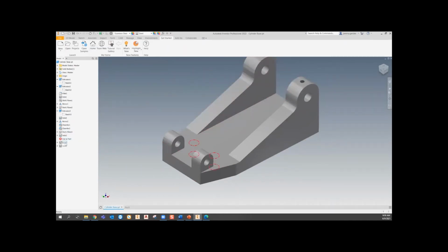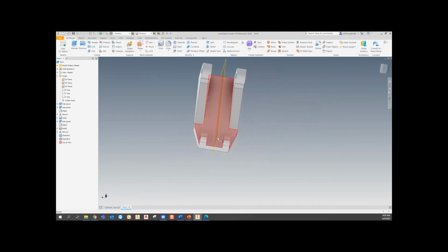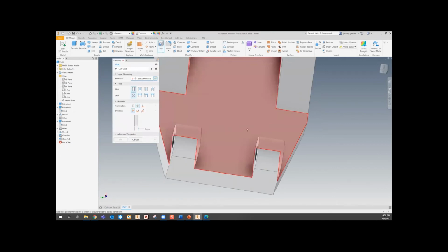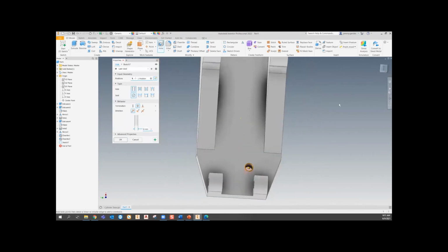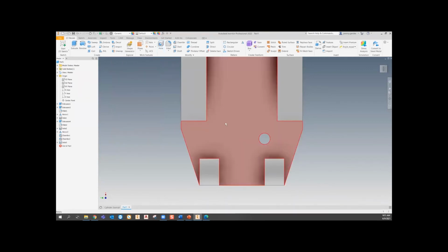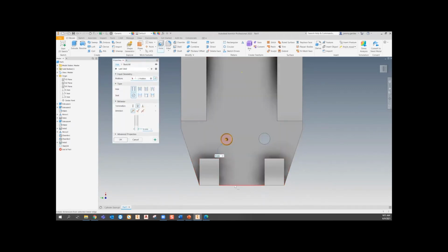And we'll do these 2 holes now. So when I go to place a hole, pick the surface. Now, since I don't have a center to go off of, I need to select 2 dimensional locations for it, 2 edges, 2 planes. So I know from this edge, it's 33. And then from this edge, it's 0. So again, 33. And you'll be tempted after you enter that first one to just hit enter, but you need to select both locations before you do that.